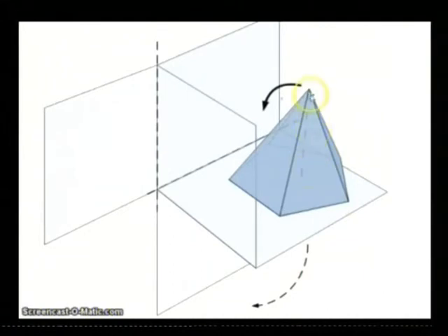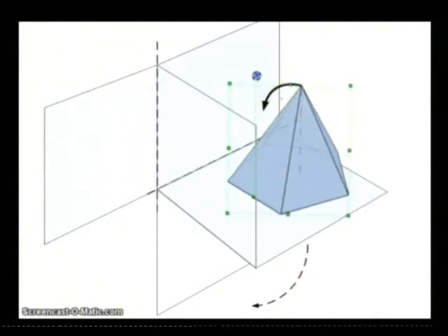So if you think here, if you hold this tip and lift this pentagonal pyramid, then you have to lift it from the top in such a way that it makes 30 degrees from the base and this horizontal plane. Okay, so that's the second part of the problem. So if I lift this one like this, then the angle between the base of this pentagonal pyramid and this horizontal plane is 30 degrees. Okay, so that's the second part of the problem.